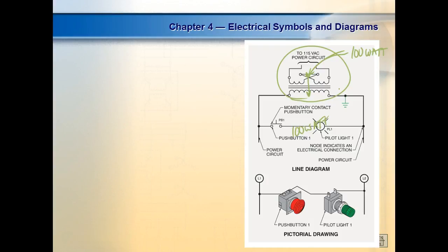And this gets people confused because people say, well, if you raise the voltage to the load, then the current goes up. But we're not talking about the load, we're talking about the source of that current. What sets the power and the current? Well, the load sets the power and the current. When you run a load, don't think resistors, think about motors and stuff like that. Those things are designed to run at a certain voltage and produce a certain power at that voltage. If you don't give it the right voltage, it's not going to produce the right power, right?